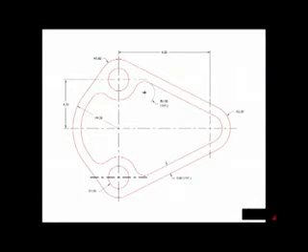One of the benefits of having a pen table is that you can customize AutoCAD to your own office standards. Most offices will configure a pen table to be used for all of their plotting needs. For now, as a beginning student, it's probably best to stick with the monochrome pen table such that all of your line work will plot using the color black.